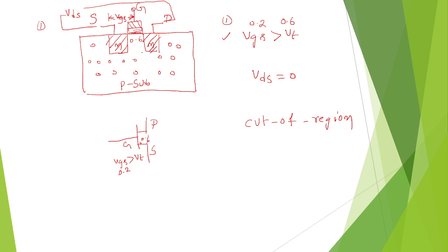And coming to the second case, you can see this here. Same thing. The transistor has either a P substrate or an N substrate. I am taking a P substrate, and to design the gate terminal, deposit the polysilicon material. This is the polysilicon material. And to design the source and drain terminals, diffuse the electrons into the P substrate. These are the electrons. In the second case, of course, this is named as source, gate and drain terminal.